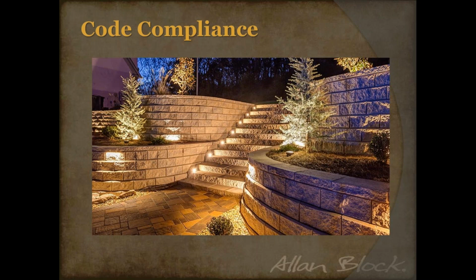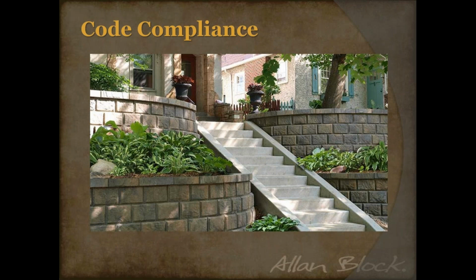Truly, if you're looking at that code requirement, I know guys, especially if they're doing commercial work or some residential work in cities that require cast in place steps. Okay. I love using segmental retaining walls because it keeps that solution dynamic and you can really work with it. But here you can see they cast the steps first and then they butted the walls up to it. And so there's ways to provide that solution, especially when you're talking about code compliance.